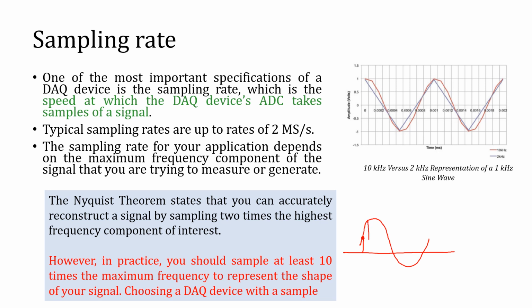After 1 microsecond it takes the second sample, after another 1 microsecond, let's say it takes the third sample. So those are the samples it has taken. Built in, it has the ability to hold that level in terms of a sample and hold circuit, and that is why it is converting only that particular sampled value within the conversion time.